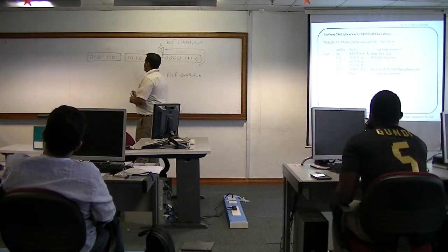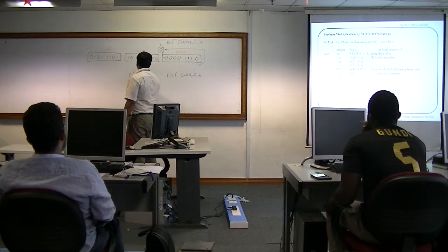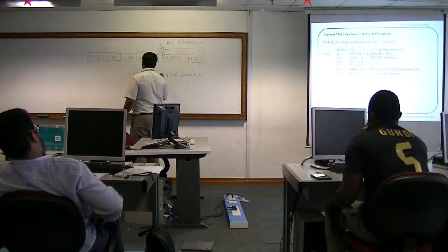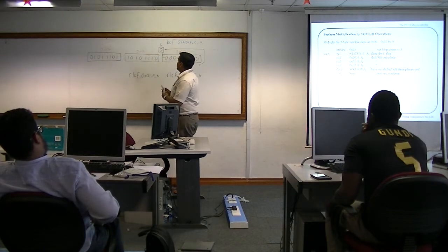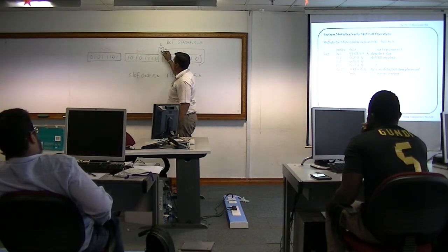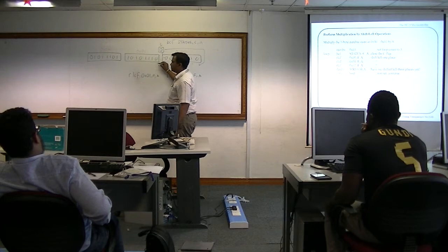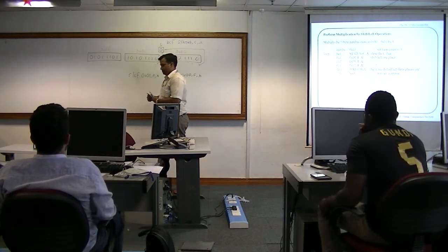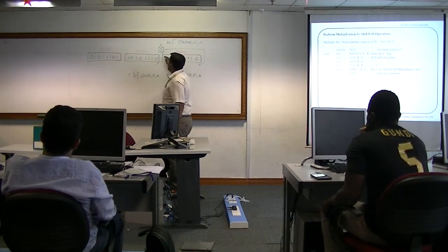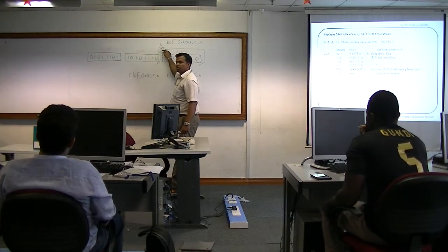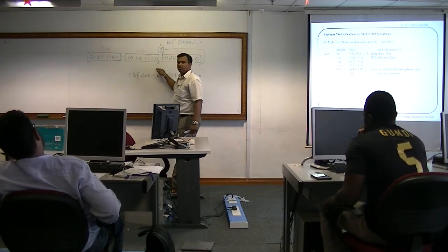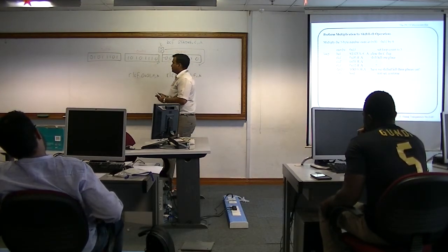Then when you do this one, rotate left through A, the 0 which was pushed into carry now comes where? Comes here, right? So this is pushed correctly. So the carry is actually used to transition the 0 from the most significant bit to the least significant bit.